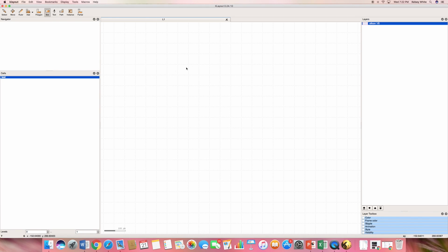And now what you're doing is we already have a cell, which was formed when we defined the panel or the layout. And this cell is really our diagram of what we want to make. And this layer is where that cell is going to go. So if we just want to make the simplest sort of thing, like a box, we can just make a box like that. Okay, we made a box. Now we want to be able to edit it sort of at the micron scale, and we might want to add features to the box like cuts or additions or holes or maybe all sorts of things.